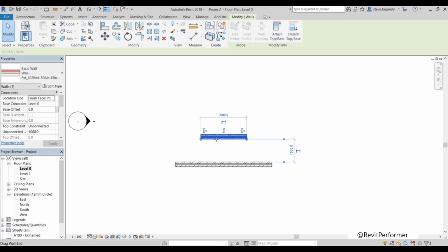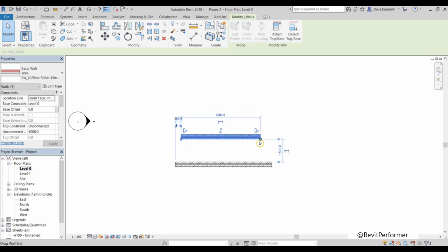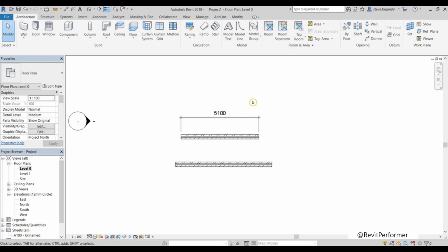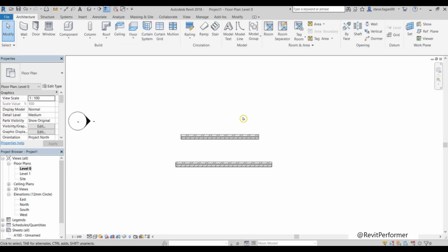As well, we have the grips, which I can click and drag to extend out the length. I can also add an angle with those grips, as well as the temporary dimension. Below it, there's another dimension symbol. If selected, we'll make that temporary dimension into a permanent dimension. To then remove it, we'll select it and delete it. I deleted it using the delete key on the keyboard.